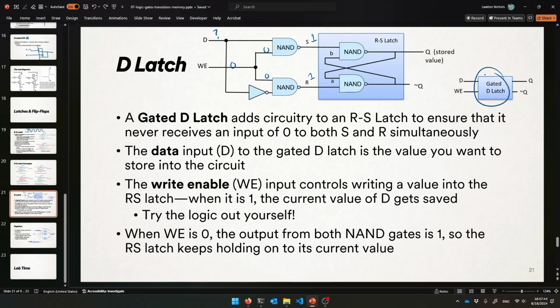So now I have this box that I know how to make if I ever need to, but now I can chain those at a higher level of abstraction. Isn't that cool? And so deep down there's that RS latch inside of there. I can use that, and deep down inside of those are NAND gates, which contain transistors. We can go as deep as we want to, but it's better to zoom out.